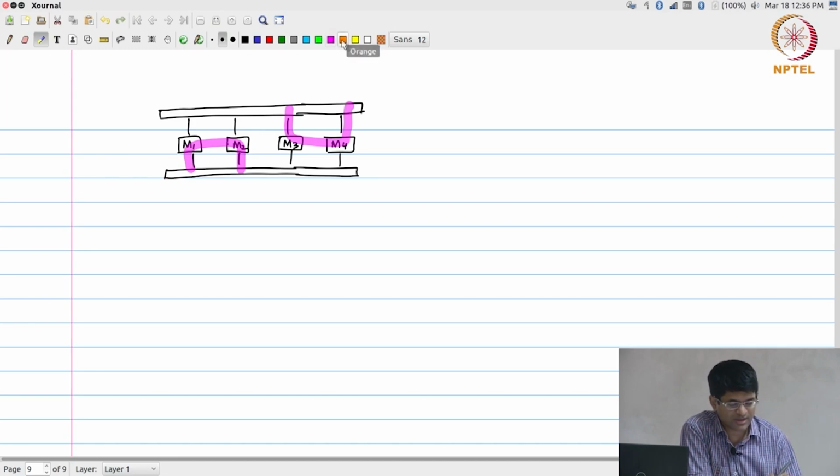You could also have another situation where, for example, M1 talks to M4 and M2 talks to M3, that is also possible, right. So, multiple different combinations of this sort can happen at the same time, right. It still does not address the question of whether M1 can talk to M2 and M3 at the same time. That may or may not be possible, that is now more a question of how M1 is implemented. So, multiple buses, in other words, is one way of doing it, right.